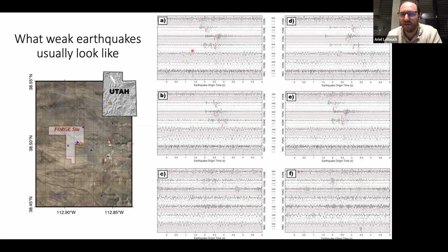And if we look at the top, we have 7 stations, each one has 3 components, Z, so vertical, east and north. If you look at the top row, you can see events that are relatively clear. You can pick the P wave, the S wave. Middle row, it starts being a bit tricky. I did not pick those, a real seismologist picked those. You can probably still pick things, and in the bottom, it looks like, well, like noise.